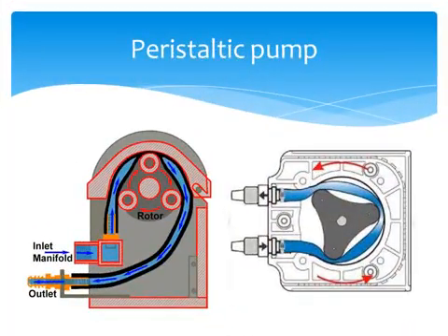The fluid is contained within a flexible hose or tube fitted inside the pump casing. The actual pumping principle, called peristalsis, is based on alternating compression and relaxation of the hose or tube, drawing content in and propelling product away from the pump. This process makes a peristaltic pump an accurate dosing pump or metering pump, with an equal amount of liquid dosed each time. The liquid being pumped never comes into contact with any moving parts, because it is totally contained within the reinforced hose or tube.